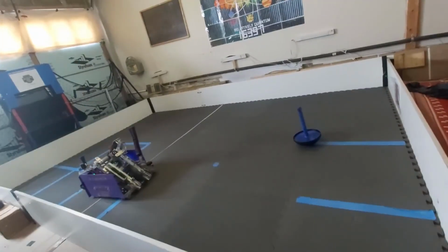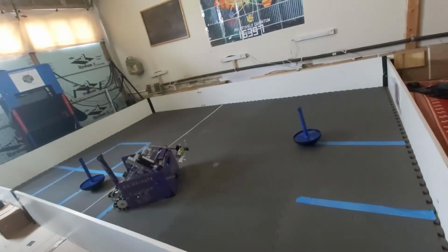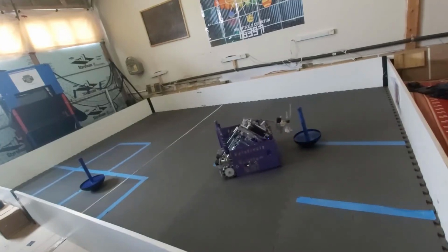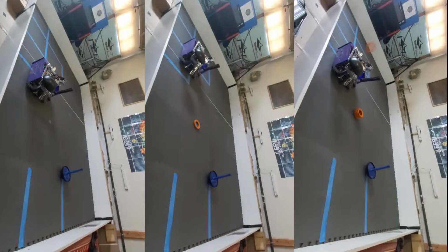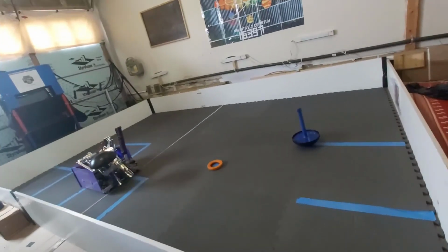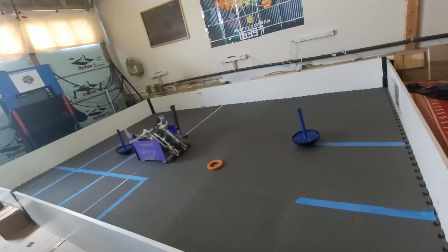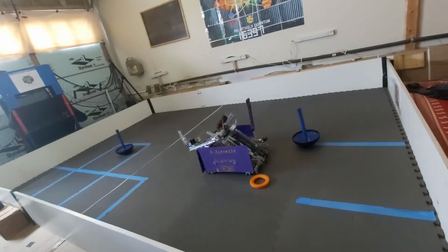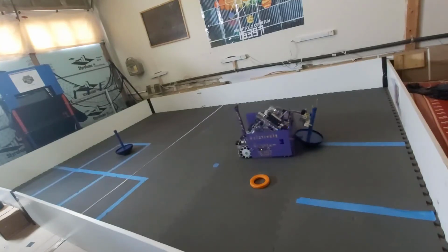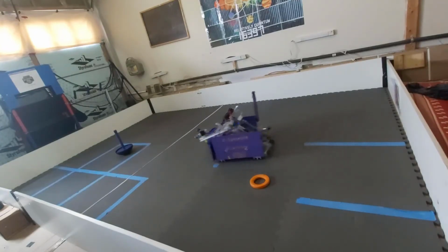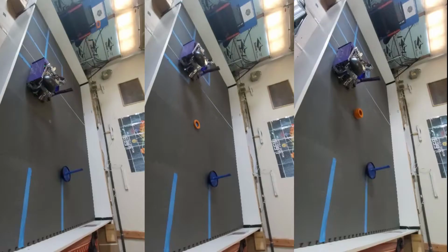The routine for square A then places the wobble goal inside box A, then backs up into the second wobble goal, using the distance sensor at the back to just come in contact with it, and then drags the second wobble goal into square A as well. B is similar. It strafes to align with the B square, then deposits the wobble goal in it. During strafing, the gyroscope automatically corrects the angle of the robot, since when strafing, without preventative measures such as these, the robot tends to drift drastically. It then drives straight to the next wobble goal, again using the distance sensor, turns and picks it up, and then deposits it in square B as well.